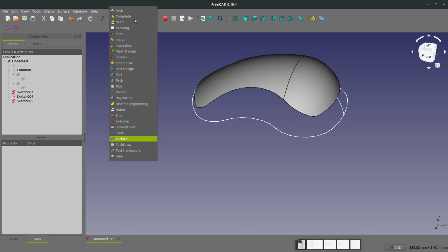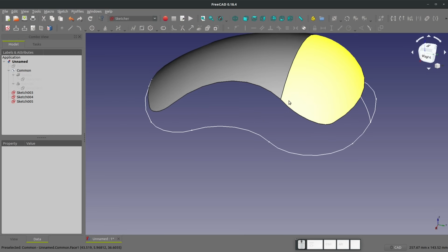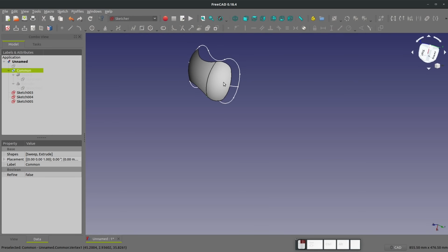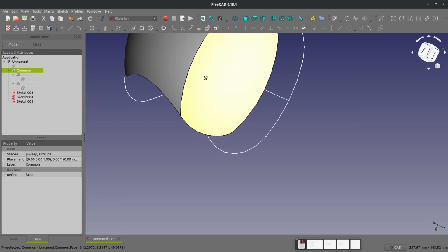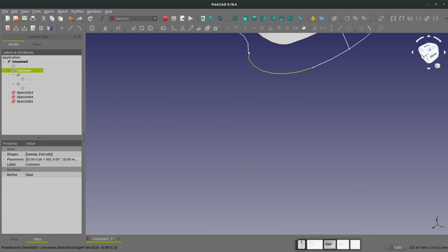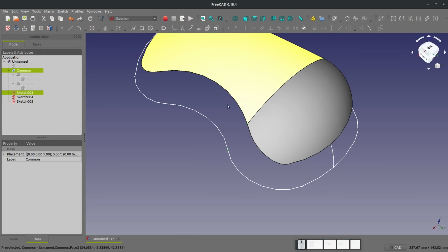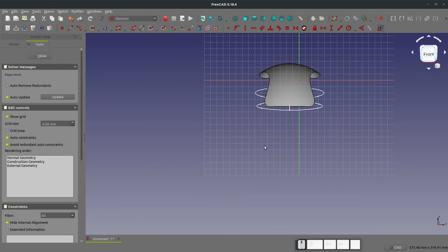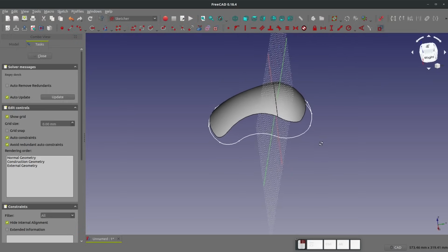And I want to show you one. And this will also help make the surface a bit smoother as well. So I'm going to create, in the sketcher, I'm going to select first 3 points. I'm going to select that point right there. I'll select this point right there and this point down here. So I've got these 3 points selected, and as you know, 3 points makes a plane. So I go to create a sketch, 3 points plane, and we notice we have a plane now that goes through all 3 points.